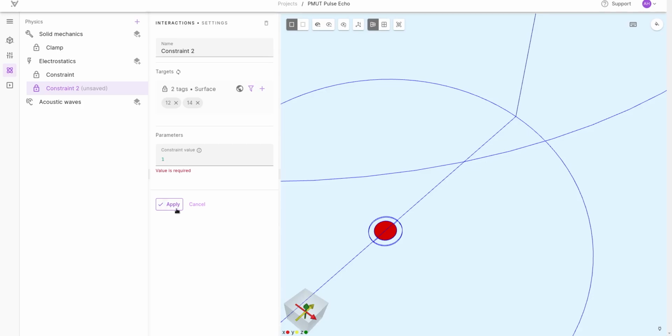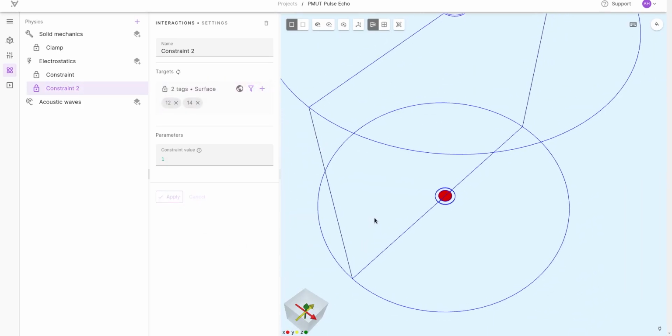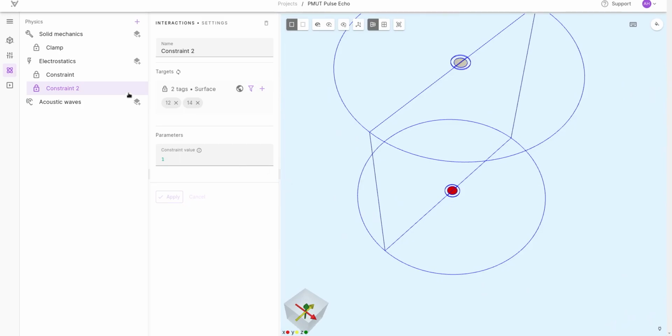and I will actually show how you can also use the script to define any driving signal, for example a pulse or a wavelet or a ramp or whatnot, piecewise defined if you want to. So for now I just use a dummy 1, and in the script I will modify it. So that's the signal, and this one was the ground. If you put the right name, you'll also have more clarity in the script regarding what is what.